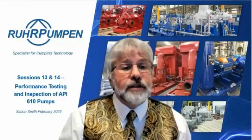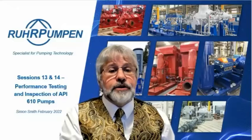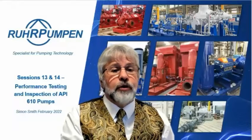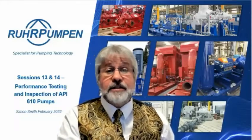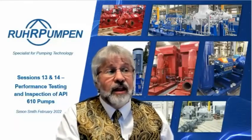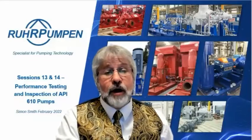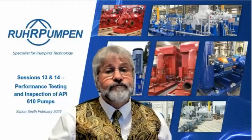Raghupathy Singaraj says, if impact test is specified for low temperature services per API 6.12.4.3, what components are to be tested? That's for you to decide and specify. You might want it just to be pressure boundary parts. You might want other parts to be tested as well. I would think just pressure boundary normally.